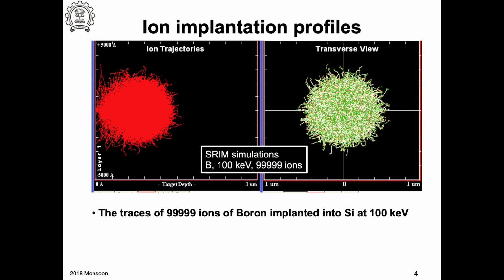So what I have done is that you have seen the implanted ion distribution in the previous slide, right? And you can do this count of ions at each location. So I'm drawing a line through this 0, a line that is horizontal to this axis, along the point 0, because that is where you introduce the dopants. So you get the count, and then you can translate it to the concentration per unit volume, and that's what is plotted here.